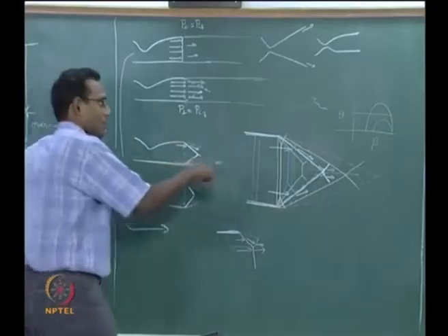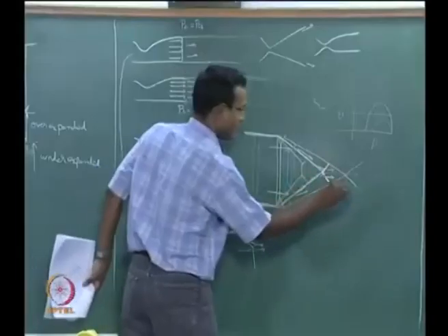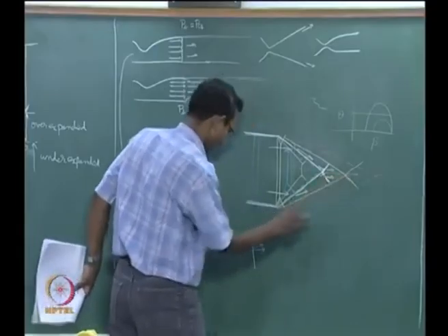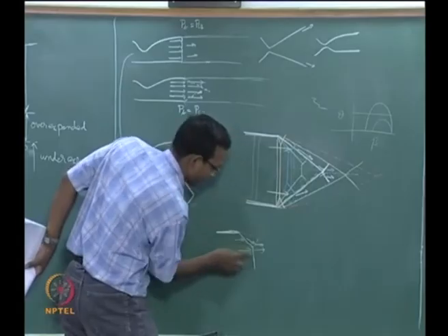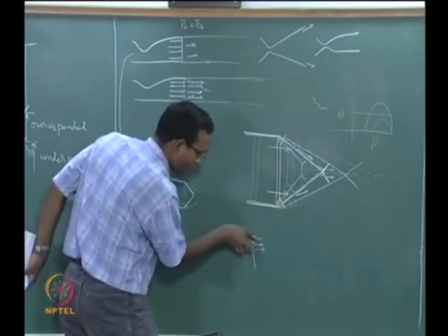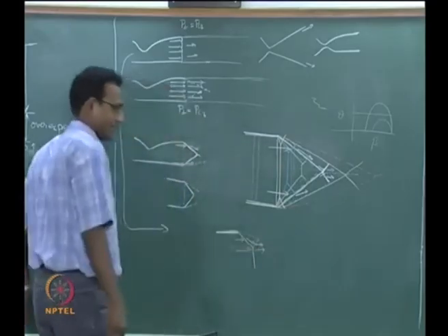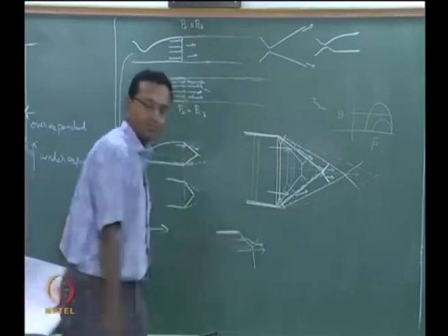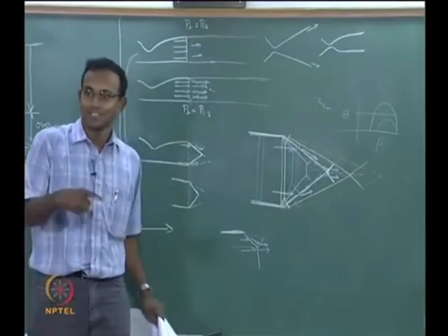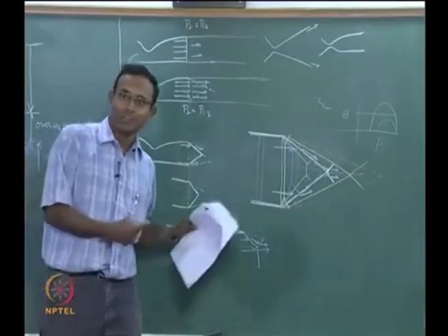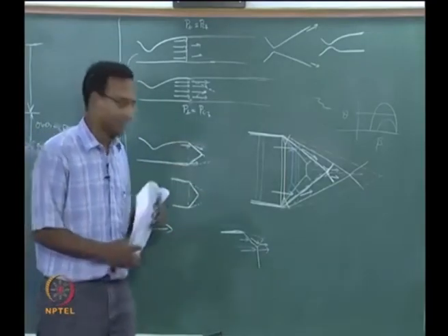How do I think about this in another form? I have drawn all these shocks, but I said that specifically I have drawn this particular shock, it bounces off this way as a Mach reflection, and I stopped drawing the shock just outside the final streamline. Why did I do that? That is the next question. I am slowly getting you involved in every detail of the problem, okay.